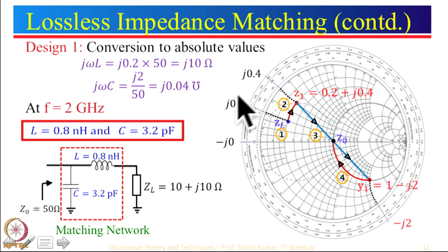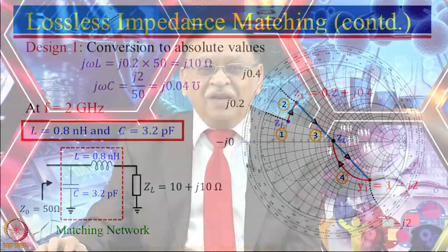Now, till now frequency has not come into the picture. So we can now substitute the value of the desired frequency. Till now this design is valid whether you do it at 1 megahertz or 10 megahertz or 100 megahertz or 1 gigahertz. Do not try to do this at 10 gigahertz or beyond, because beyond 10 gigahertz or so these lumped element values are very, very small.